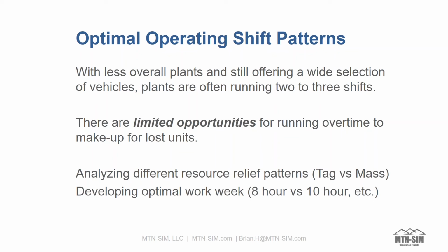often becomes very, very complicated without a simulation. And if you were trying to do this deterministically, it's going to peter out very quickly. So in the simulation world, we can really test out various build schedule patterns and sequences, and look at our overall sequence, and we can come up with the most optimal release pattern that gets us close enough to our original customer order, but also achieves our overall throughput targets.